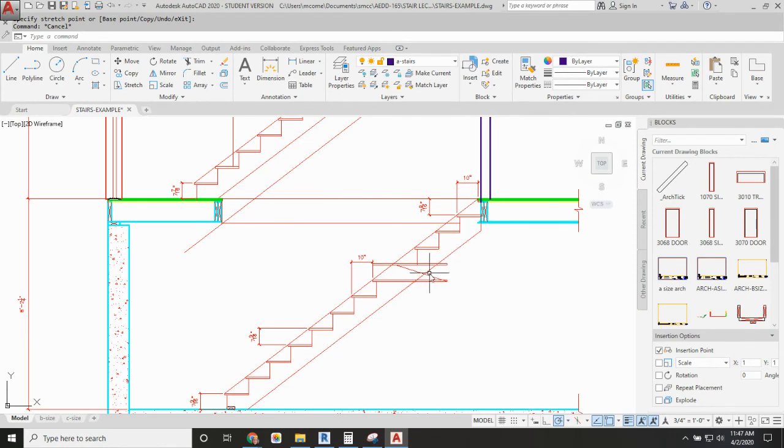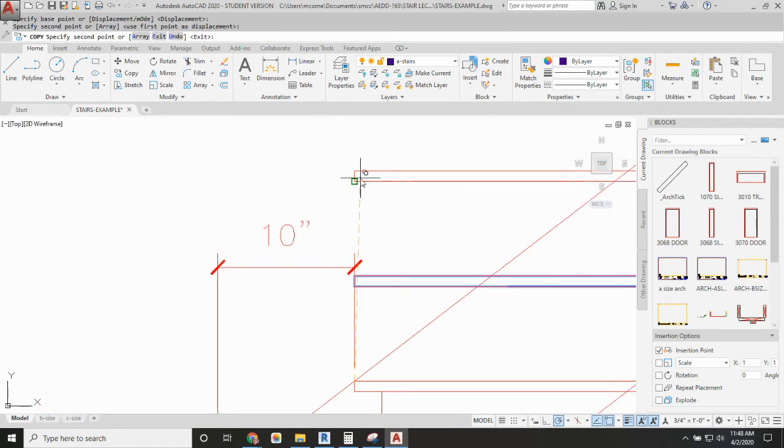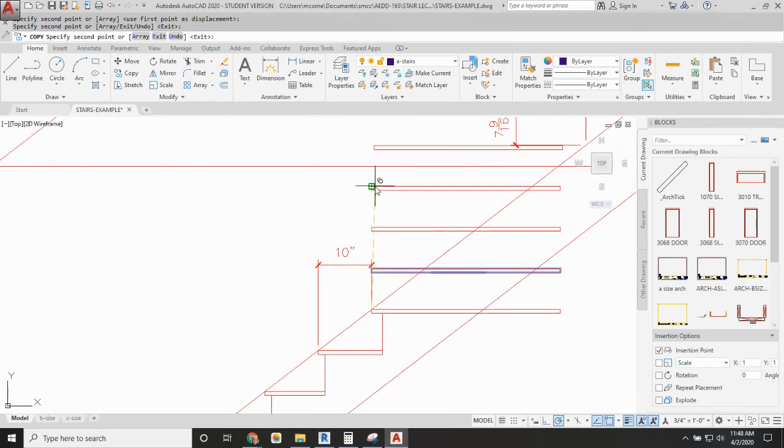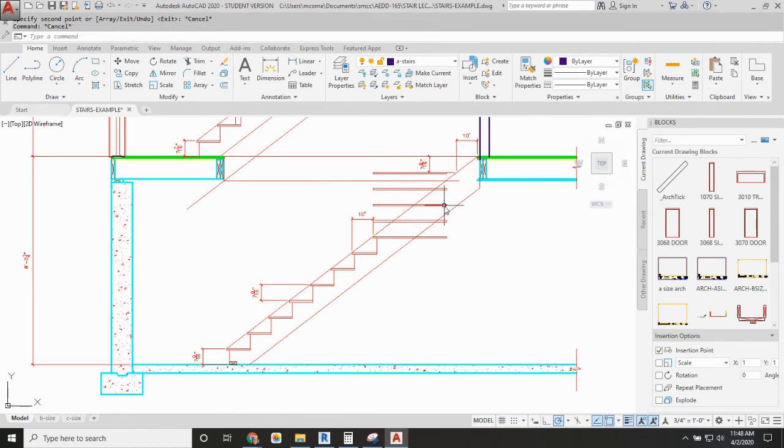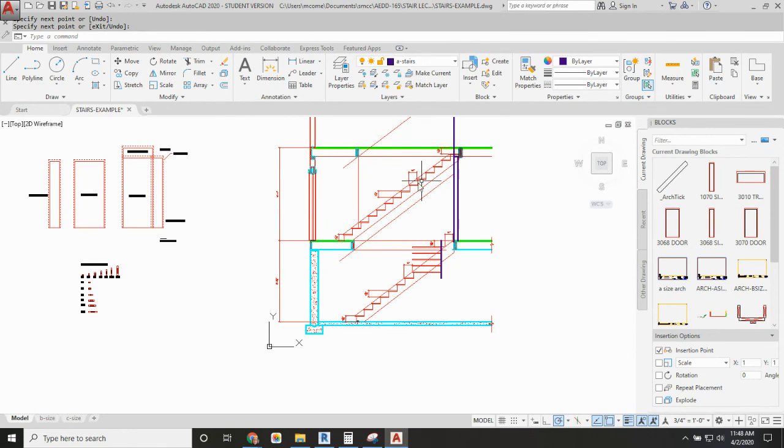changes because we're changing direction, and all of these would just match. So from here up, we'd see the stairs facing us or from behind until we got up to that level. So now this is an example of an L-shaped set of stairs. There would be a landing here, go up the stairs, hit the landing, change direction, and continue up the stairs that way. So you see that the dimensions that you come up with for that straight set of stairs are the critical ones, and then we just reconfigure them.